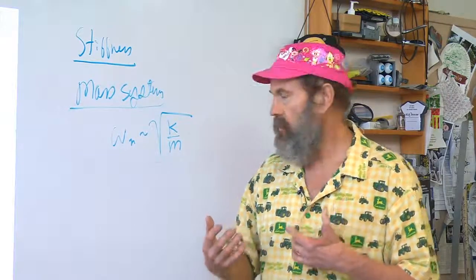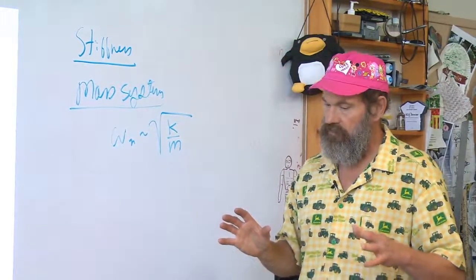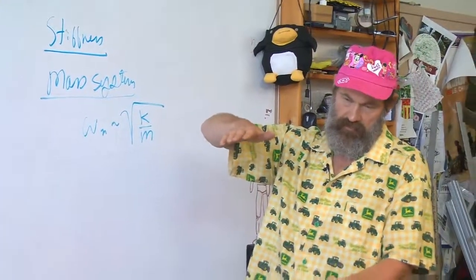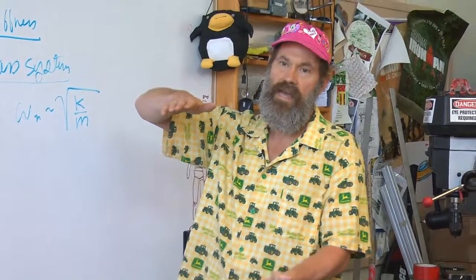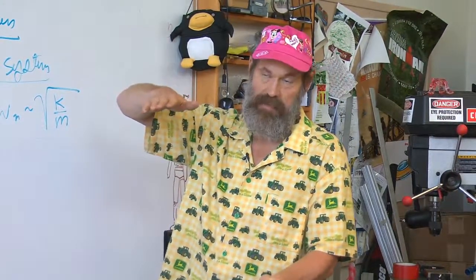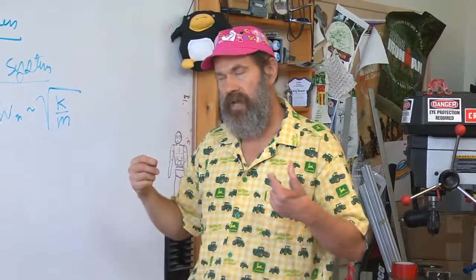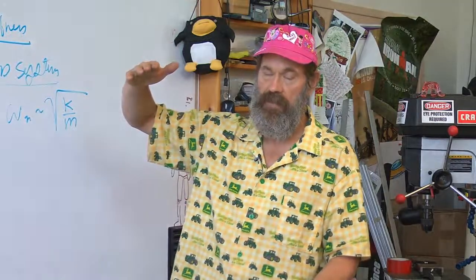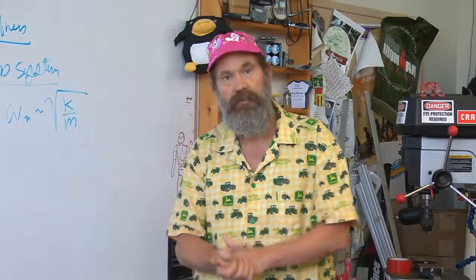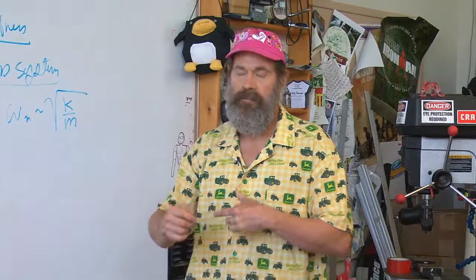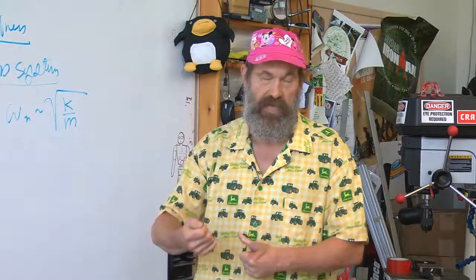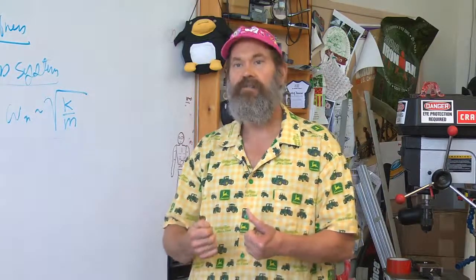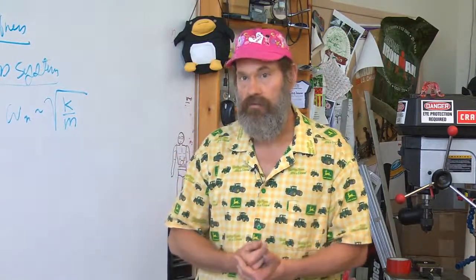And as long as you're designing your structure with the intent of using the neutral axis theorem to keep most of the mass away from the neutral axis, like for example it's an I-beam, and you have provisions for how you can add more mass far away from the neutral axes of the members or add in diagonal stiffening elements without obstructing the motions that are intended, you at least have a strategy or countermeasures for the risk of natural frequency too low.